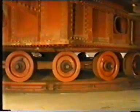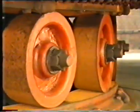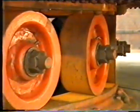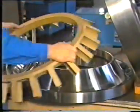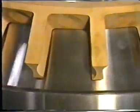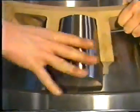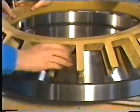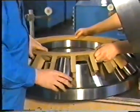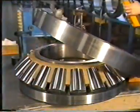As the roller track of the inner circle is shorter than the track of the outer circle, the rollers are tapered. Due to sensitivity with respect to tolerances, deformations and subsidence may happen, but not all rollers are load carrying. This disadvantage is removed in the modern constructions by replacing the rim bearing by a spherical roller thrust bearing. It consists of an inner and an outer ring in which a carefully machined cage is fitted. In that cage, the spherical rollers can rotate.